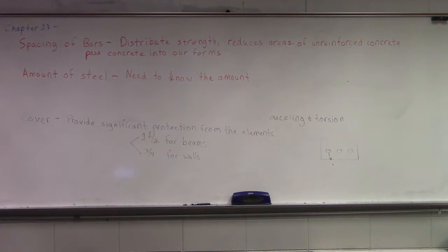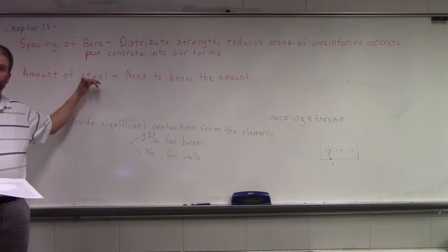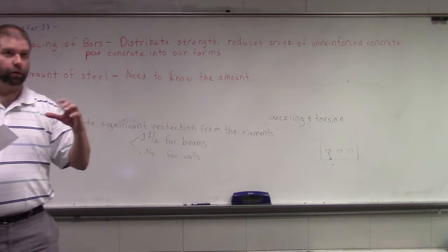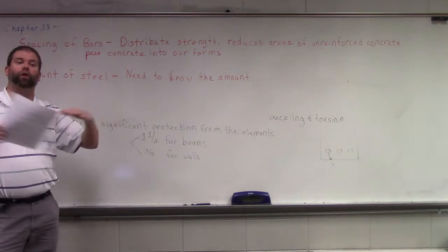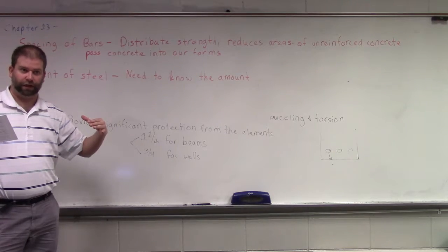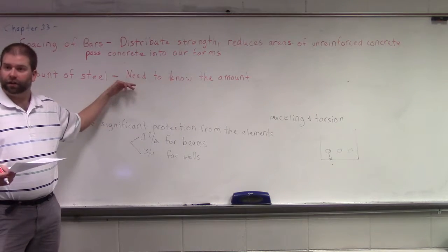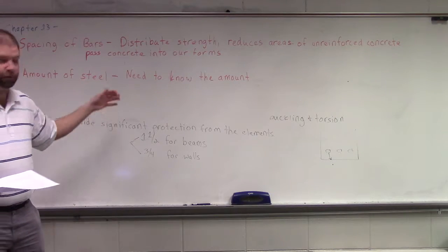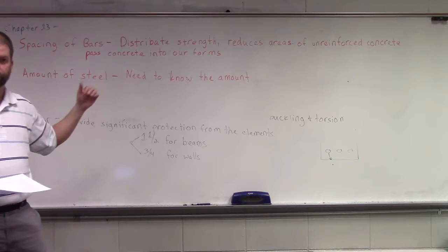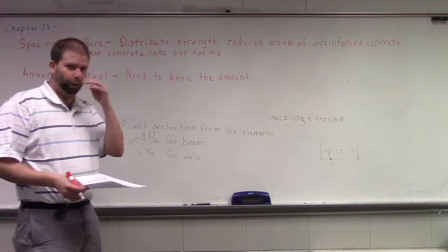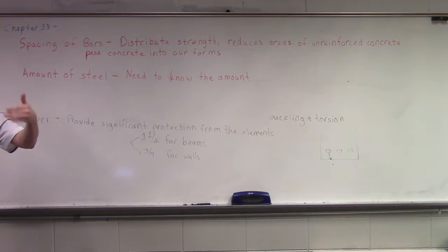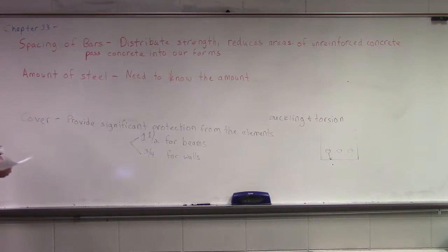Exactly, yes. So the first step is figuring out how much steel we need. Even before that, we need to figure out the total area of reinforcing that we need. Then, given the limitations that we have, how wide our beam is and how much cover we have, we can look at our selection. That's a portion of the assignment: once we determine the area of the steel and know the limitations of the beam width, what type are we going to select and place?